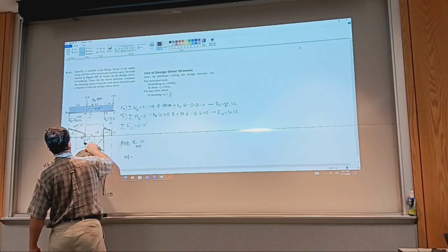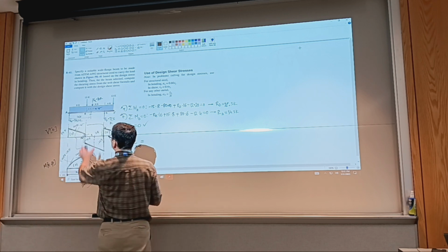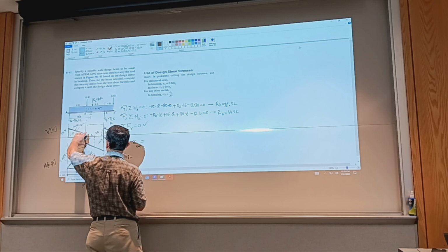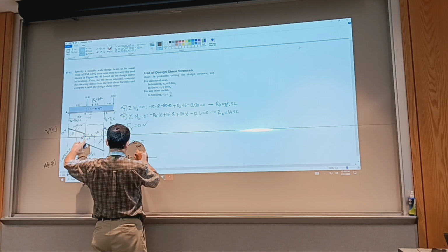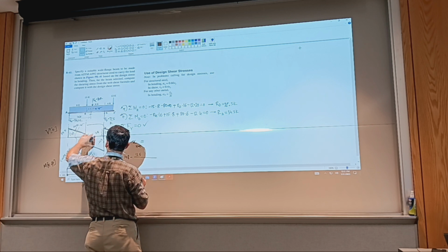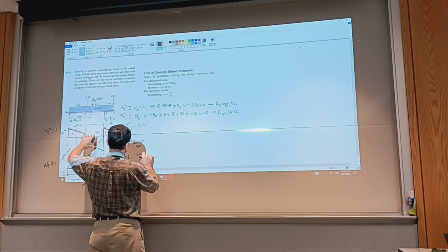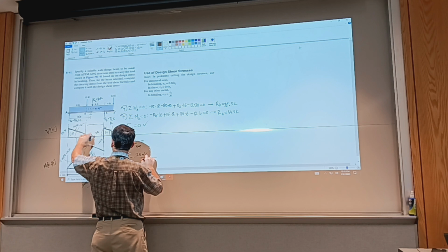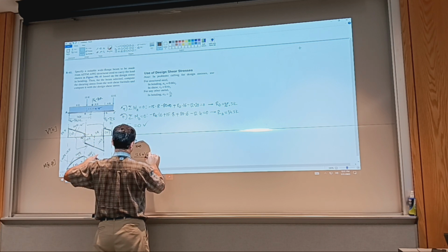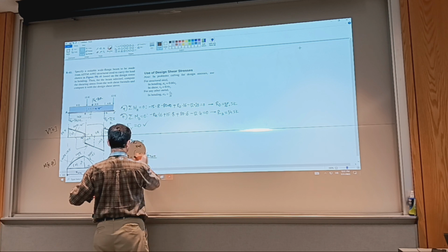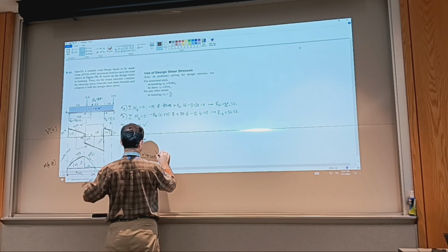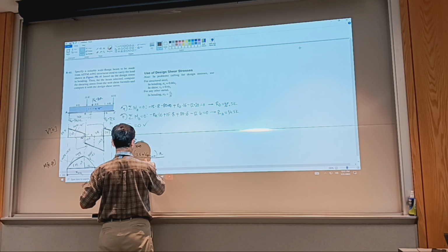So how do I get shear at A? We'll have this piece. The area of the trapezoid is going to be 12.5, I take the magnitude, times this V at, well, I could say x at M equals 0, times A over 2.